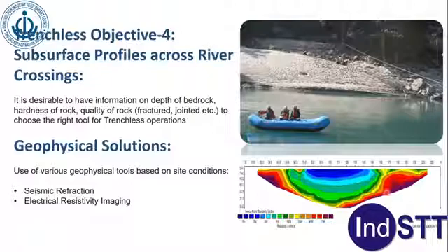Now, seismic refraction was giving you more flat interfaces. Seismic refraction tomography is an improvement on that, where you are able to see a better profile of your rock. And this is a wonderful example of use of seismic refraction tomography, where there is a shear zone here. You can see it is very small, around 8 to 10 meters. And this has been beautifully picked up using seismic refraction tomography. Now, any amount of drilling or any frequency of drilling will not give you these kinds of shear zones unless you go for this kind of continuous method of investigation.